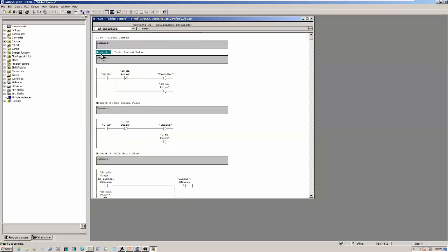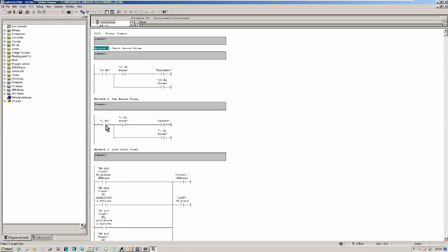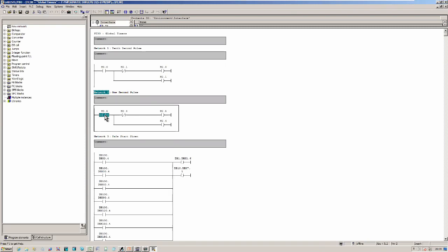What we do in this program, just quickly, is every second, it's marker byte 1.5. Remember, 1.5 was every second. Every second, it's going to put this marker on automatically, and it's going to one-shot marker 2.5, and this part here will make sure it's only one shot every second.